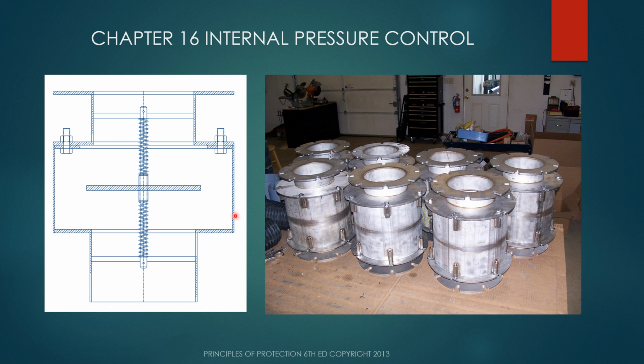A typical blast valve functions like this. If the overpressure comes down here, this wafer plate seals against here and stops that sudden burst of pressure. It also works for the negative part. There's a negative part of this. As the blast wave passes, there's some suction, and this comes up and seals against here. So that's how a blast valve works. They should be stainless steel or aluminum. They are subject to rust because they're connected to an air manifold which draws moisture down.